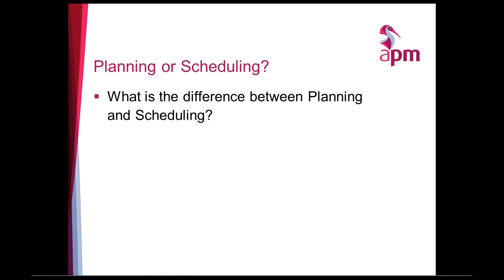Scheduling's more of a science. Scheduling's about deciding what the start and finish dates are, determining the critical path, leveling resources, and determining what resources you need to use. So it's more of a science than an art. They're very closely linked, but they are completely separate activities, and often planners have both of these skill sets. So when someone refers to themselves as a planner or a project planner, that's what they're actually talking about. And for scheduling, we have all sorts of tools available like Microsoft Project and Primavera.